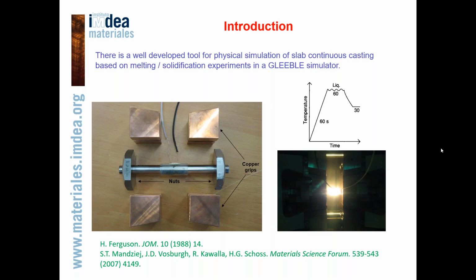So in the case of the samples molten and solidified using quartz tubes, we have mainly solidification direction growing along the axis of the samples, whereas in the case of the samples molten and solidified in ceramic tubes, the grains are formed and grow not only at the edges of the molten section, but also at the bottom and on the sides of the sample. I don't know if I could explain it.